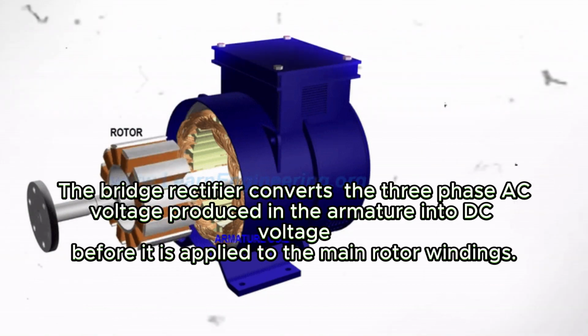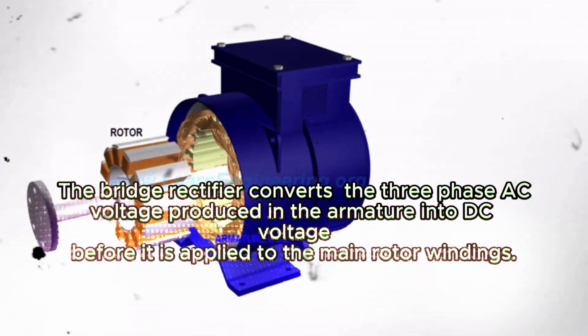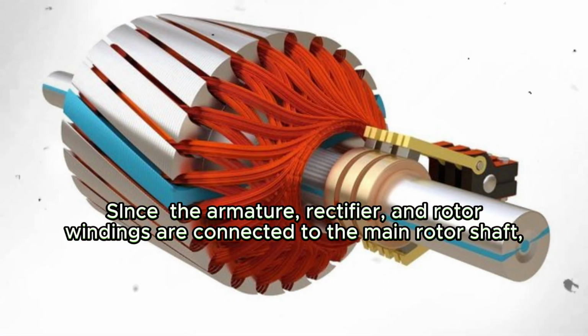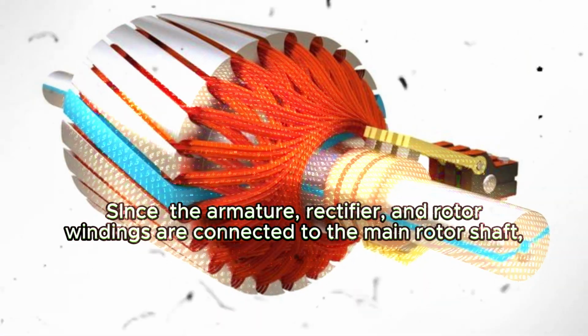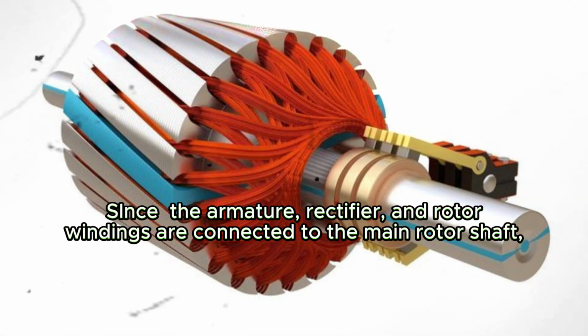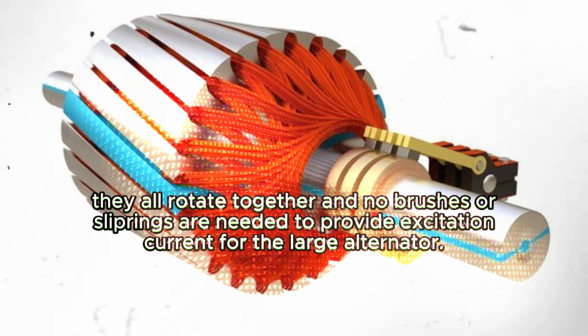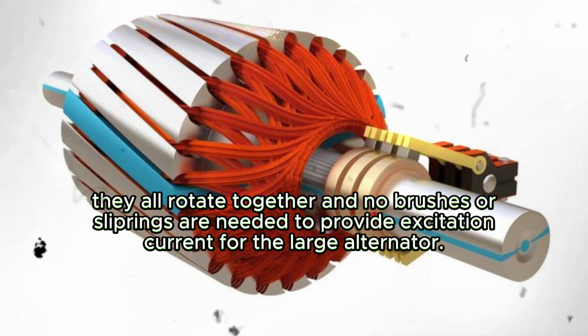The bridge rectifier converts the three-phase AC voltage produced in the armature into DC voltage. It is applied to the main rotor windings. Since the armature, rectifier, and rotor windings are connected to the main rotor shaft, they all rotate together and no brushes or slip rings are needed to provide excitation current for the large alternator.